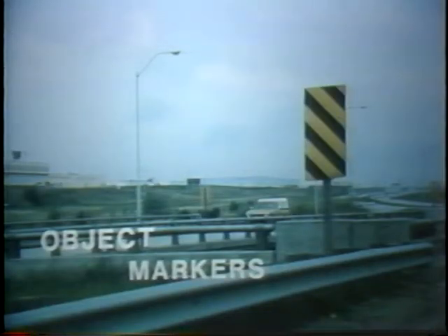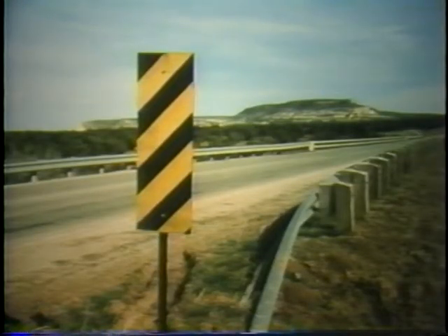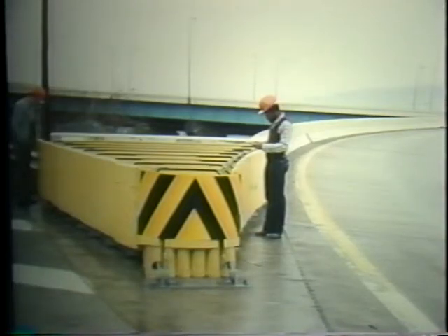The object marker is used to call attention to a hazard on or near the pavement surface. This object marker points out where the driver should not drive, so the object is a negative delineator. Upstream ends of longitudinal barriers, as you see here, are one of the situations requiring a hazard marker. When traffic can pass on either side of the hazard, the center object marker, shown here, is often used. For center markers, a combination pattern is used. The nose of crash cushions must be well delineated.